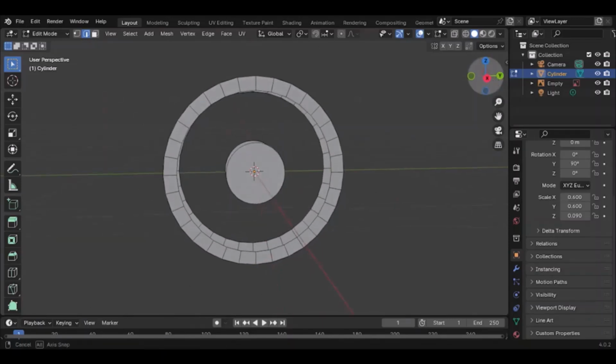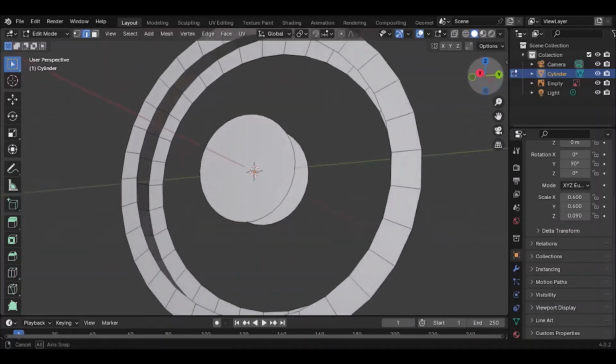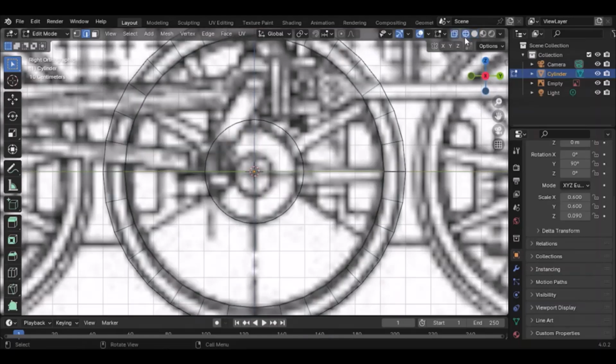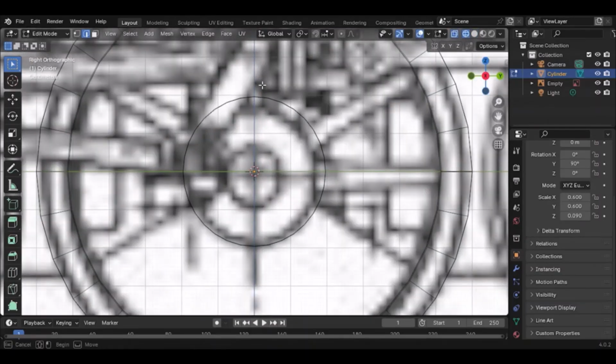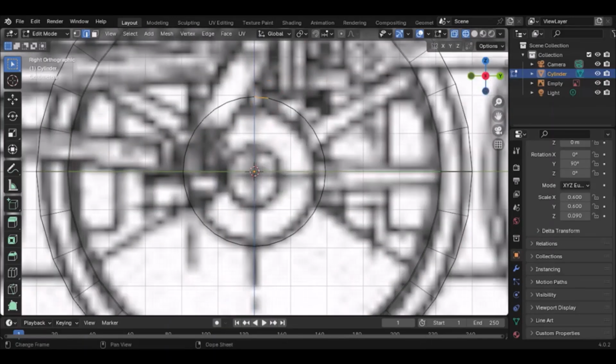Now that I've gotten all the guys that know what they're doing here, I guess we should start. So to do that, I'd recommend going into wireframe, which is this little button here. Then just hit select and then the letter F, and there should be a little face there now. So I'm just going to do that because this can take a little while, so I'll check back with you once I do that.